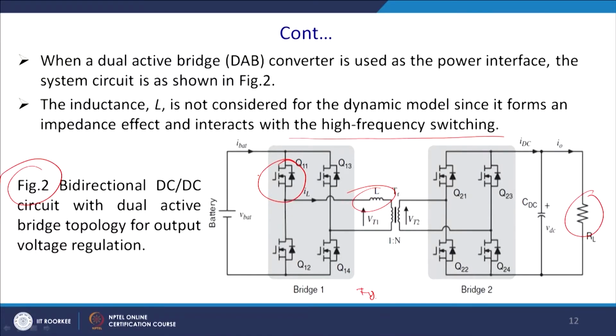If this converter is IGBT based, then it can handle power up to 100 kilowatt, and of course the switching frequency required is lower, and you may be operating a few converters in parallel, which also is required to be taken into account. Ultimately while designing this, the battery will give you the intermittent extra power required from the solar or this thing.